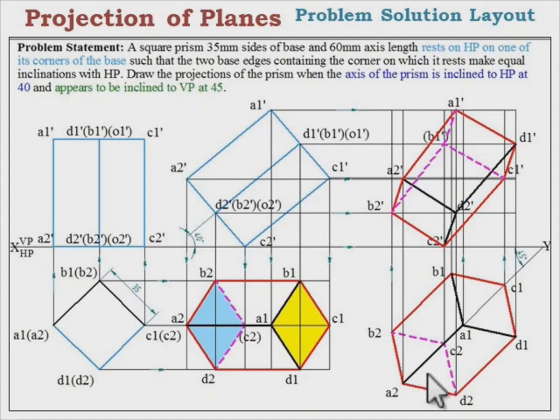Now we are viewing in this direction to draw the front view. We will draw the vertical projections from this top view and horizontal projections from the front view and mark the points as discussed. All outer boundary points are marked with continuous thick line.